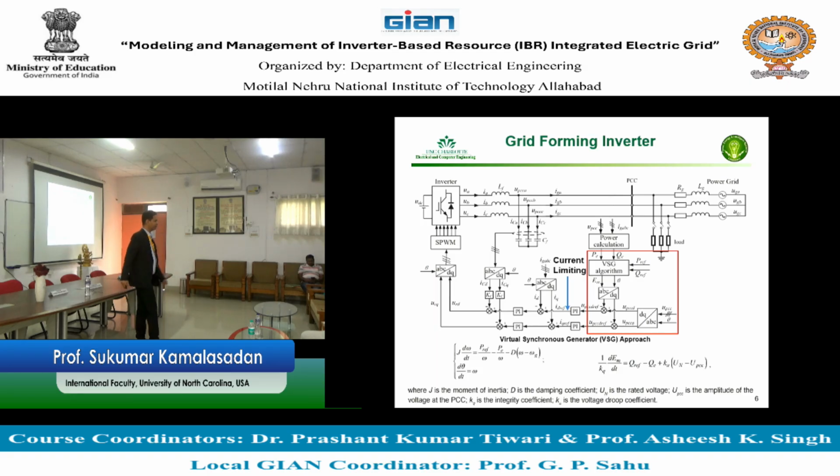One way of generating the voltage and angle is to look at how the voltage and angle are generated using a synchronous generator and write down the synchronous generator equation, all math, no real machine, no real spinning mass. Using a mathematical approach, you can generate a voltage and angle like a synchronous generator, and that process is called virtual synchronous generator. And whatever you generate for the synchronous generator, for example, the inertia you generate, that's called virtual inertia. Virtual damping. You add virtual to everything. Will it work? Yes, it works.